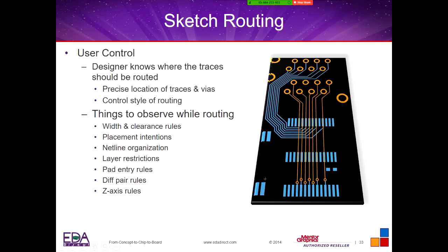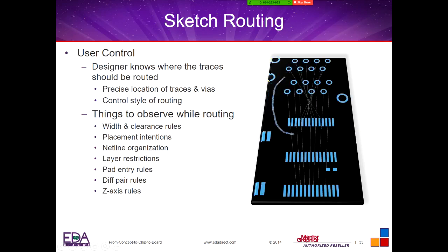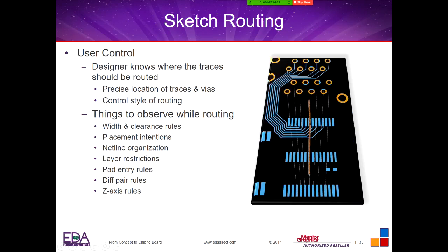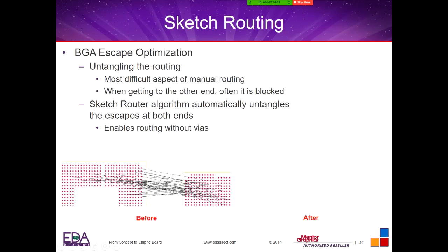So we've got all kinds of things that we can change, set up in here, whether you're routing your differential pairs, or how you want the pads or the traces to be routed into the pads. We've got Z-axis rules, and everything works with the constraint management tool.